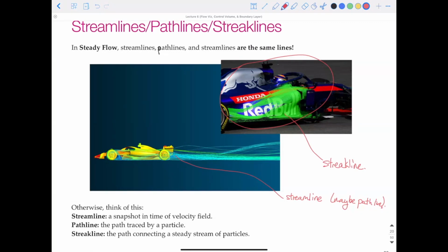Is a streamline a photo of one particle? So a streamline is a photo of all particles in the fluid flow, but it's not necessarily a photo of the particles themselves. It's a photo of the velocity of the particles. So it is the velocity that determines where that streamline is. The path line and streak line, we can visualize those as the particles themselves, but a streamline is a bit more abstract because it's not the particle, it's the velocity of the particle that we're visualizing.